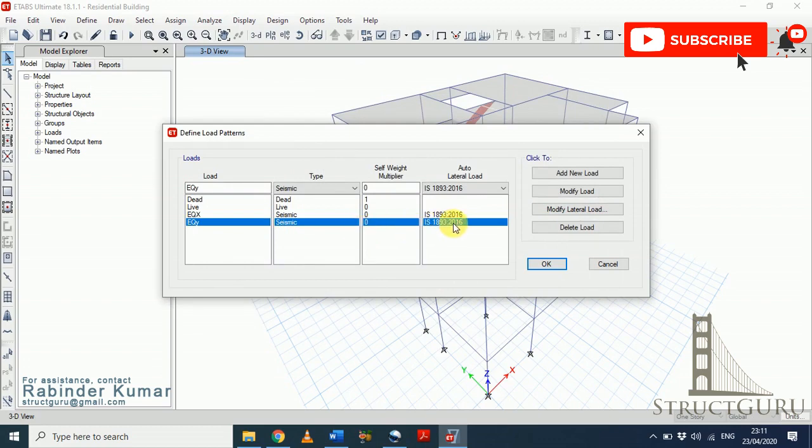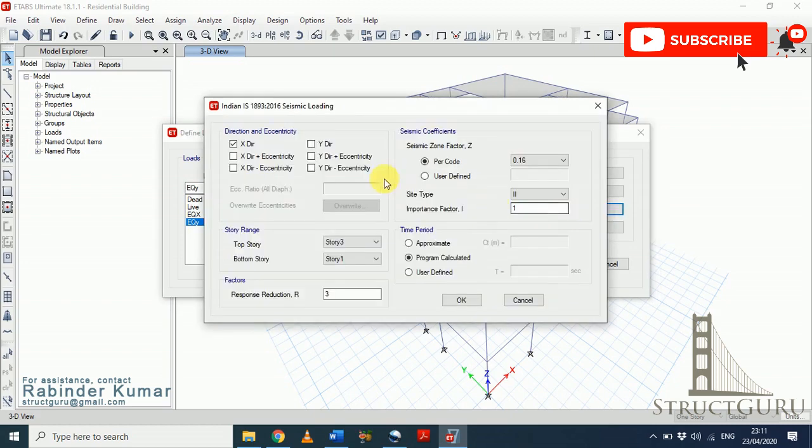To change the values in Y direction, click EQY, click Modify Lateral Load, uncheck all these parameters and check Y direction only. As per our zone factor, the value was 0.16. Our site type we selected was 2. Importance factor, as we are dealing with residential buildings, is 1.